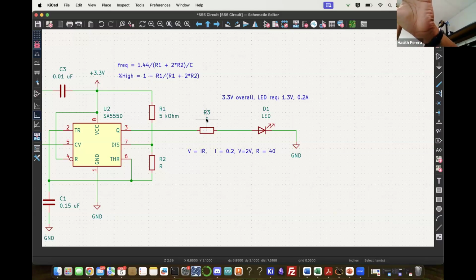But it makes no difference to the software. The only thing it cares about is what connections are made and what the footprint is. So I could choose not to document the value here, but if you wanted to, this is how you would do it. You could say R3 is 500 ohms and have that on a separate sheet.